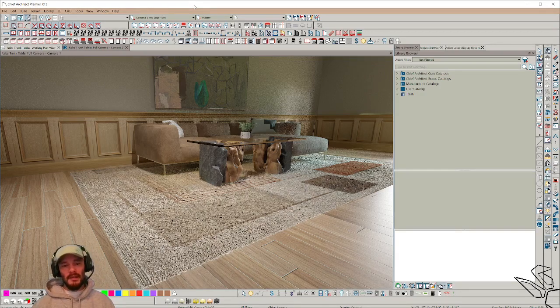And then once I brought this into Substance, we have a bunch of tools. All I did with this, and it was very quick, was I took a fur brush and changed my channel to be only on the height map, and then I painted in height on just a square item, on just an expanded cube.